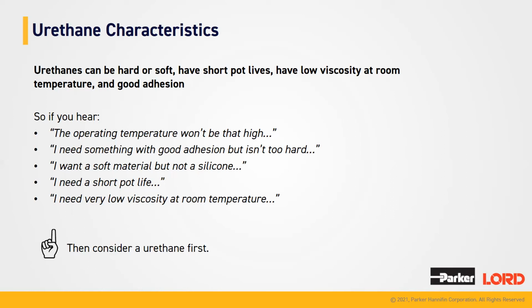In the future, when going over your options for an application, if you hear such things as the operating temperature won't be that high, I need something with good adhesion but isn't too hard, I want a soft material but not necessarily a silicone, I need a short pot life, or I need very low viscosity at room temperature, our urethanes may be the solution you're looking for.